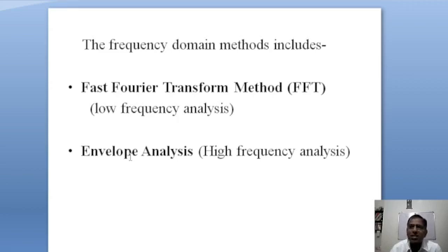For analyzing such a modulated signal, because the signal gets modulated as the fault frequencies are carried by the structural resonance frequencies and the amplitudes are modulated, we require envelope analysis. So generally high frequency analysis is carried out by envelope analysis. So envelope analysis is one of the advanced signal processing techniques that we require for analyzing a signal in the high frequency zone.